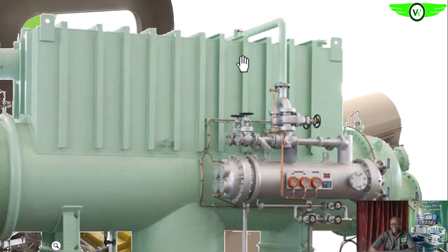So as the ejector is working, it is pulling those non-condensables from the condenser itself, or the exhaust system of the steam turbine, thereby creating the vacuum that will be needed within the condenser. Those non-condensables, along with some steam, especially during operations, will be sent to this cooler or heat exchanger. Here it is cooled further, and then the condensate will be sent back to the condensate line, while the non-condensables will be ejected to the atmosphere.